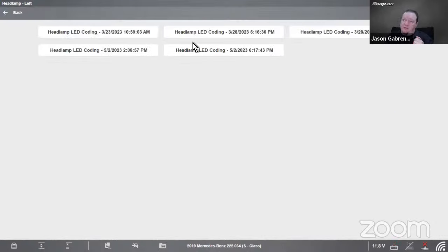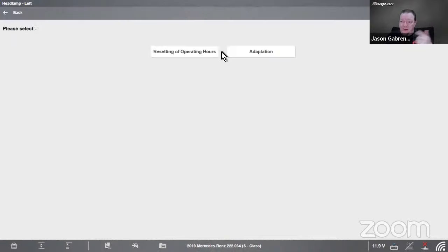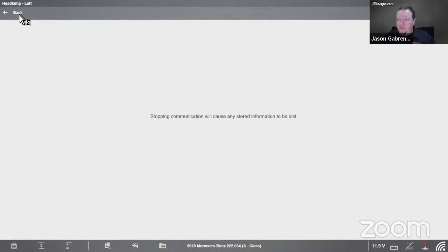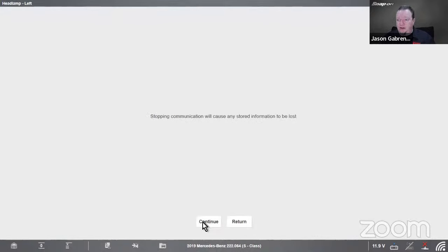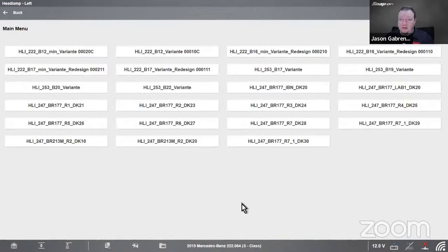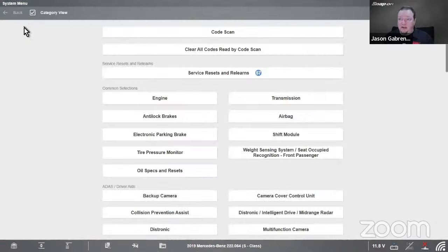And then you can see I have some from doing this class before. This one just happened right now, so I can click on that. And then it'll simply restore it from there. And we're good. Let's see, do we have injectors on this one too? Also, remember on Mercedes, we need to stop communication before we disconnect from the vehicle. Otherwise, we can have problems there as well. But let's go into engine and see if we have.